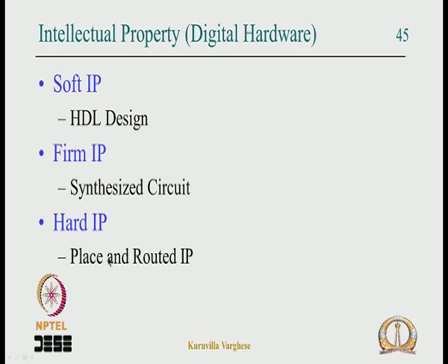The advantage with this hard IP is it is already tightly integrated, very optimally placed and routed. So it can be very fast, but you know that any change in this hard IP is very difficult because physical synthesis is over, the transistors are over, chip masks are ready. To change it is quite tough.